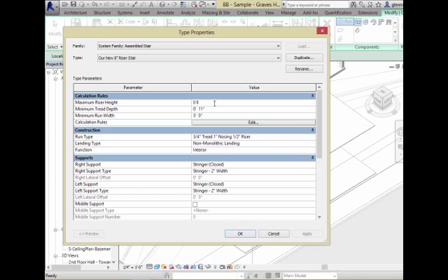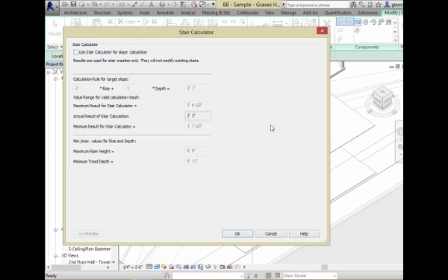And if you actually want to see the rules, they're here, where basically the rule is 2 times the riser plus 1 times the tread depth is 25 inches. That's all based on this notion of as you're strutting along, how your hips move, and where your foot's going to land. And it's all customizable.